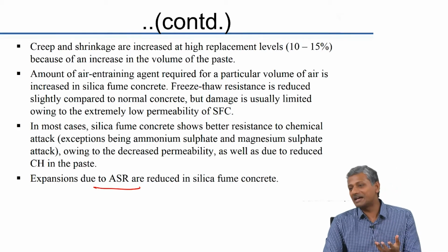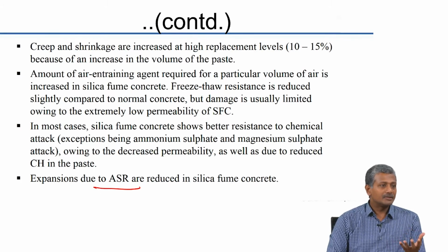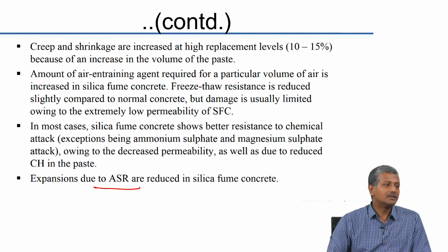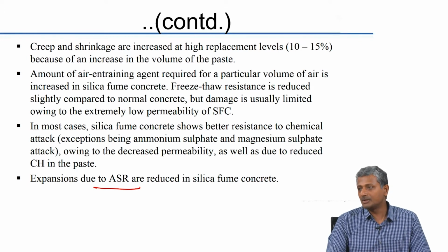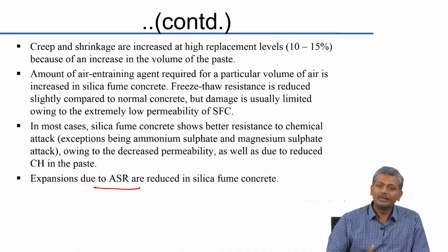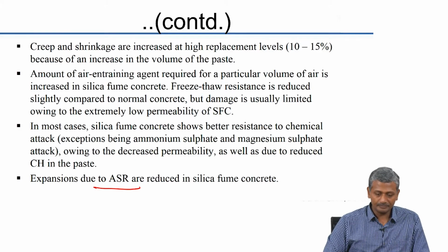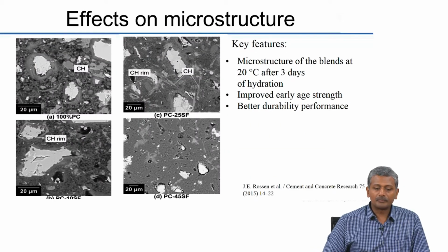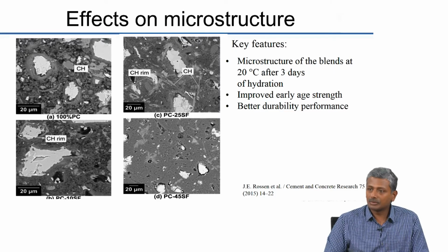So again, the aspect is that when your finely graded silica particles are used, they trap the alkalis into a non-expansive gel, because of which this alkali is not able to react with the reactive aggregate, right. And this happens very early in the process, after mixing the concrete. So this really does not create a problem like reactive aggregates do, which happens in the very long term. All right. Now there are effects on microstructure of the concrete that have been published all over the world.